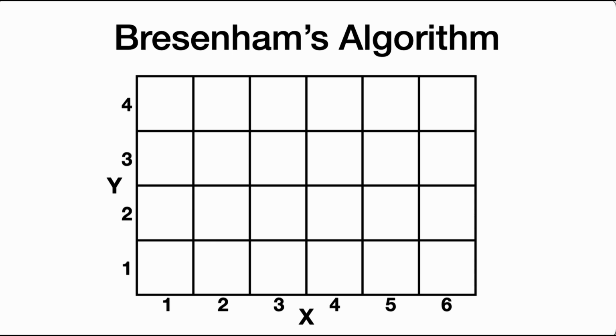One way of drawing straight lines between 2 points on a screen, which is effectively an integer screen, whole numbers only, I can utilize the Bresenham algorithm. This algorithm was developed in the 70s for plotters, and it's perfect for this LCD screen. So how do we draw a line between 2 points on an LCD screen? It seems pretty straightforward, but we've only got whole numbers when we're dealing with the Z80.